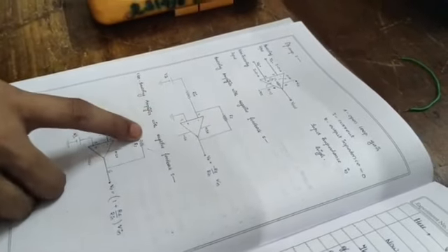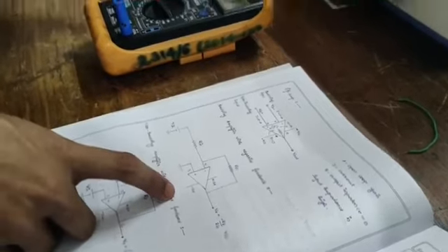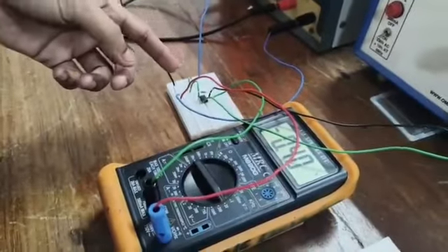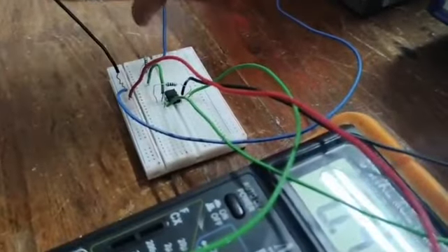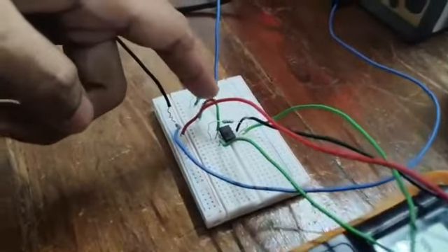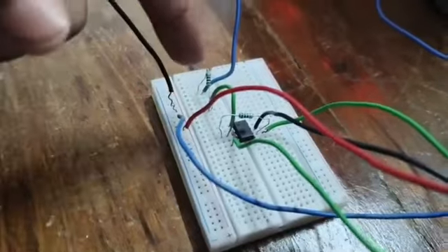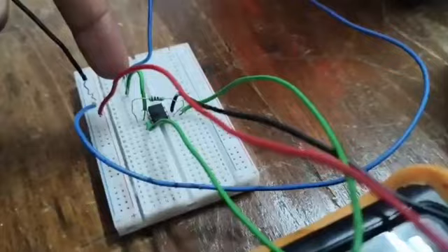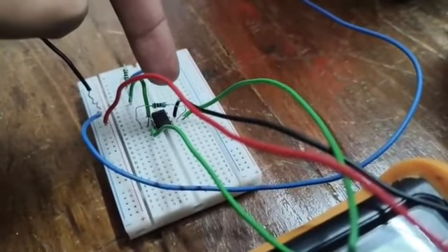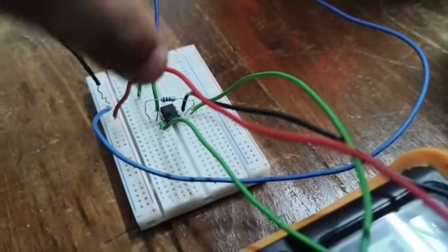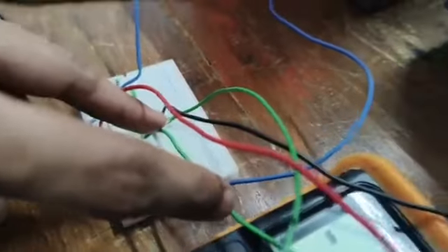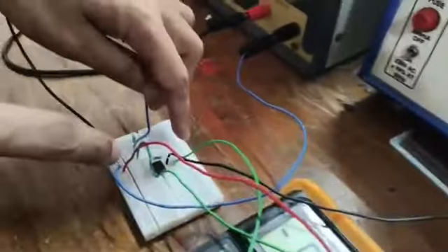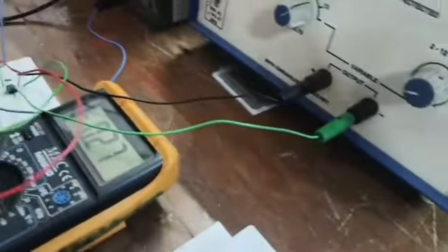Okay, so let's start the op amp as inverting part. So we can see the circuit diagram here. We have already connected according to the circuit diagram. We kept the IC chip here. From 2, we have taken one connection to one point. From there we have connected one resistance. Then another resistance is connected from 2 to out 6, and minus VCC is connected to 4 and plus VCC is connected to 7.